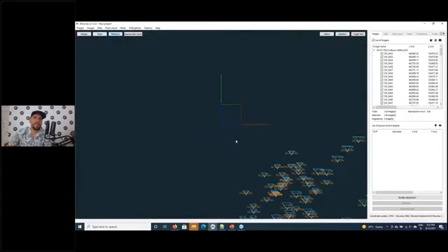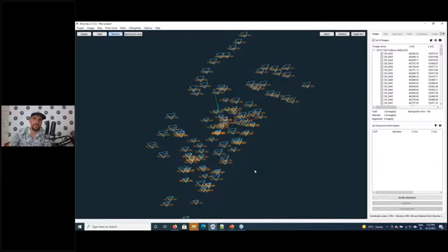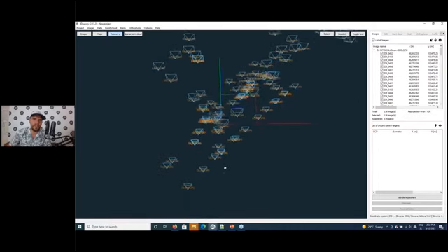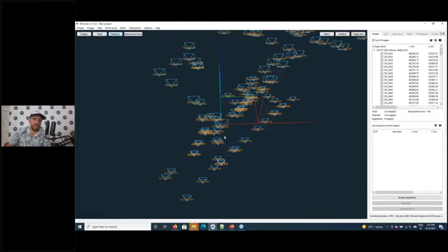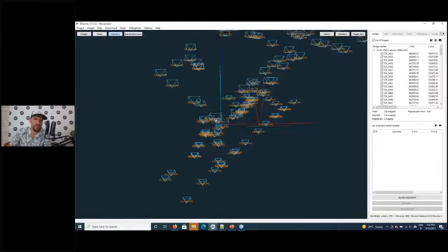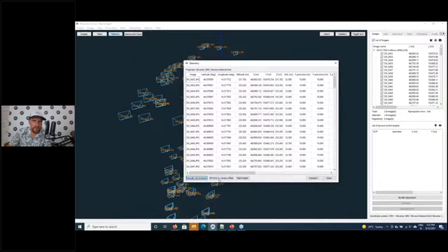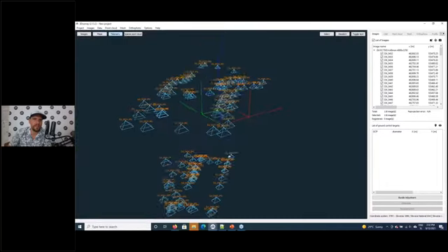Now, okay, first thing to note, if you plan on using DJI Mavic Mini drone, this one is missing the camera orientation data. That's why all cameras are pointing towards north. If you get this kind of data, you can easily fix it by going to data, telemetry, INS to camera offset, and we will just rotate all the cameras by -90 degrees. Press confirm, close, go to telemetry view again.